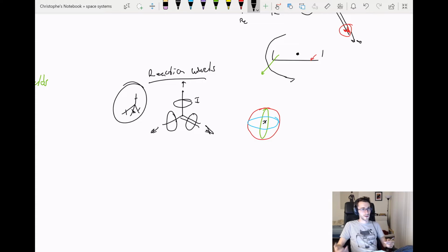Now, it's often not done. You're not often desaturating reaction wheels with other reaction wheels, because if you're going as fast as you possibly can, you don't want to compensate for that by speeding up your other reaction wheels to go faster in a certain direction. It is done, but not on a permanent basis. It's more often used in tracking of different targets. So if you're looking at something on the Earth and it's moving really, really fast, your tiny little reaction wheels can't go that fast. The reaction wheel in its primary direction will spin as fast as possible, and if you're in a tetrahedral, the other three will go, oh crap, we need to move faster, and give it a little bit of an extra boost to help the tracking of that target.